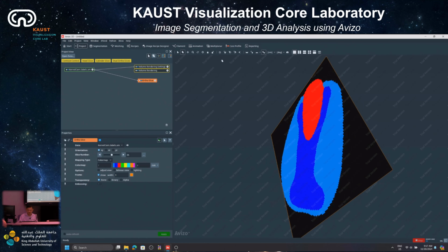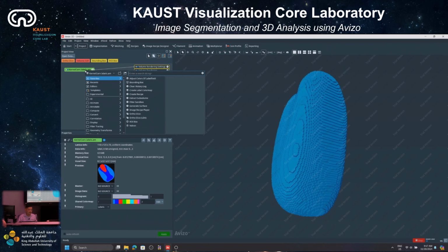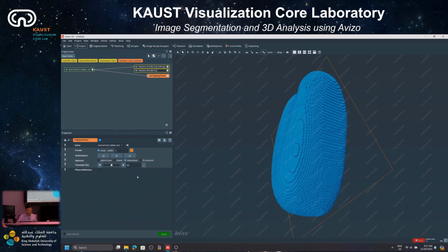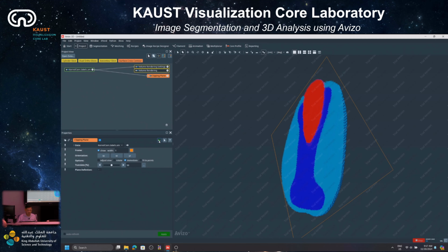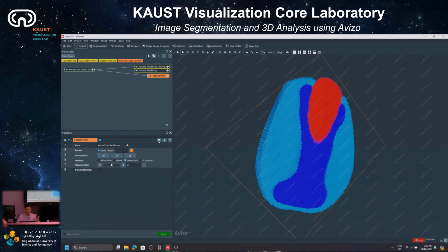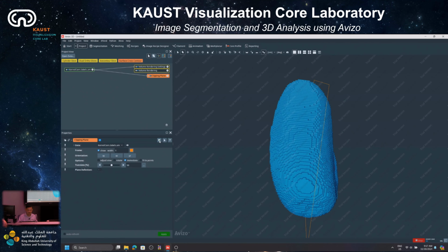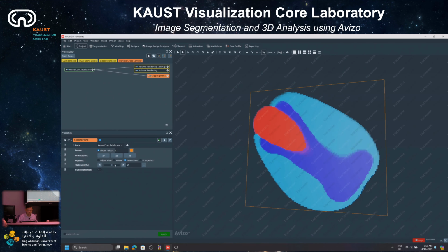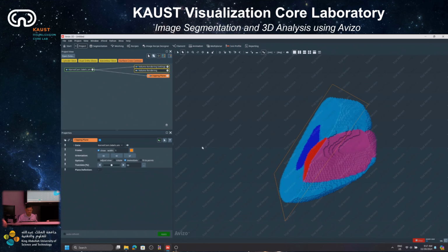If you don't want to use ortho slice, you can also use a clipping plane like yesterday. So right click and type clipping plane. So you can see the clipping effect by clip here. When you clip, it clips in one direction, and you can clip again. So change the orientation of clipping.